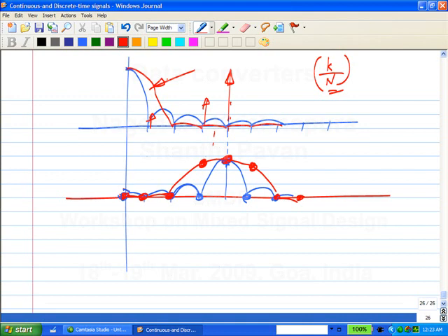And there are even other windows like the Blackman-Harris window, which is much wider here, but the energy drops off even more quickly. Okay? If you see a basic signal processing textbook like Oppenheim and Schafer, you will have plots of all of these things. Right? So that is the trade-off. You will always get these 3 points with the Hann window, but far away from it, you will get much better performance. Okay?